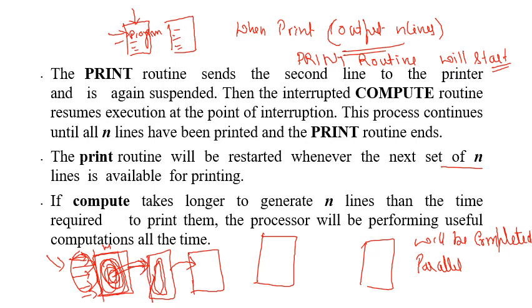So the majority of the processor time can be used in performing other applications, rather than wasting the time in checking for the particular event to occur. The advantage of interrupt is that as soon as there is a fire, it will send the signal irrespective of the condition of the processor. The processor will stop the task, whatever it is performing, immediately, and switch over to the task that has to be performed when the fire has occurred. That may be turning on the alarms, turning on the motor pumps, or alerting some agencies. The programs related to all these things can be written in this particular routine. This is how the processor time can be reduced.